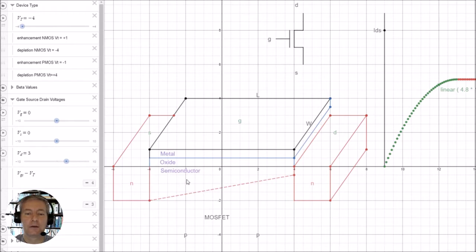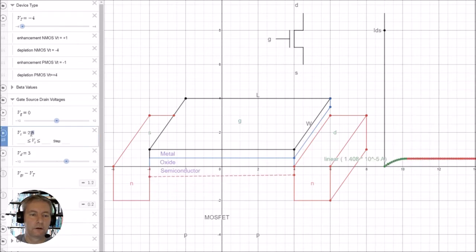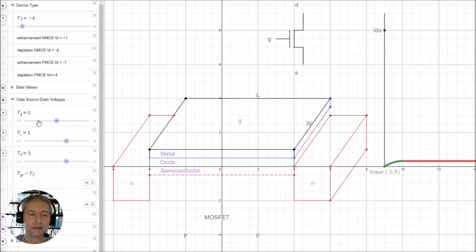So it means that if we're depleted of those holes, and the source and the drain voltage, say for example, were the same voltage, so let's make them both 3 volts. You can see here that the gate voltage sits at 0 volts. So at 0 volts, there's still a channel that actually exists below this region.